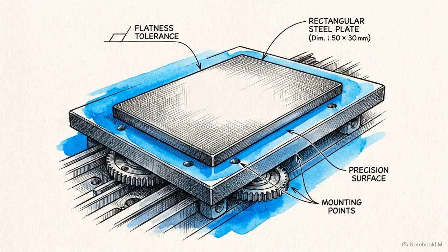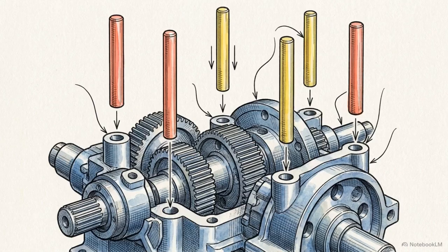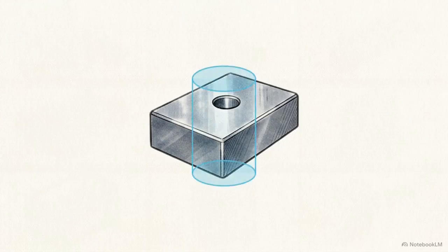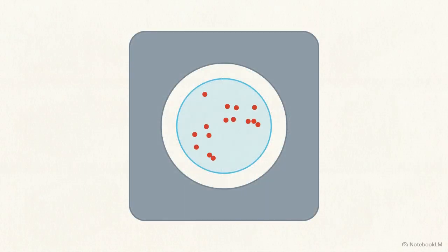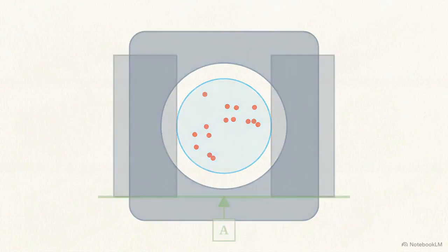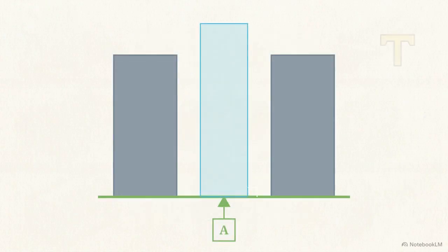When the design moves from flat surfaces to cylindrical features, like mounting holes or alignment pins, the geometry of the tolerance zone changes. Controlling an axis requires a 3D cylinder rather than two planes. This transparent vertical cylinder is the absolute boundary for the hole's orientation. Inside is the derived median line. This jagged path represents the true, mathematically calculated centerline of the actual drilled hole. For the part to pass inspection, the entirety of that derived median line must fall inside the cylindrical tolerance zone, anchored rigidly at 90 degrees to the datum.